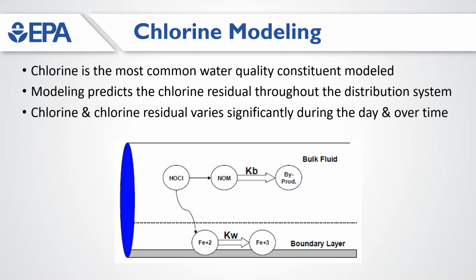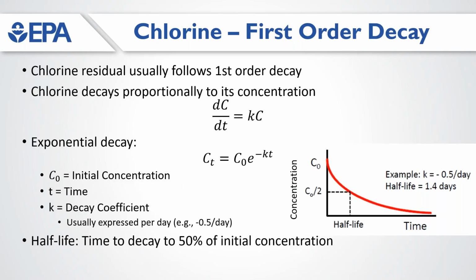But EPANET is not trying to really physically model this kind of process. That's probably likely the job of the EPANET multi-species extension. EPANET simplified the reaction, using only one single species, basically disinfectant, to model the process.